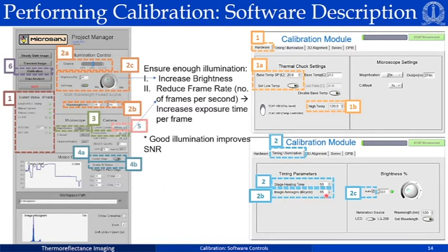It acquires 55 images in one heating cycle. So you can vary this number. The larger the averaging, the better the signal to noise ratio. Thirdly, as the measurement goes on, you must keep an eye on this indicator, because that shows whether the brightness is sufficient for carrying out a good measurement.